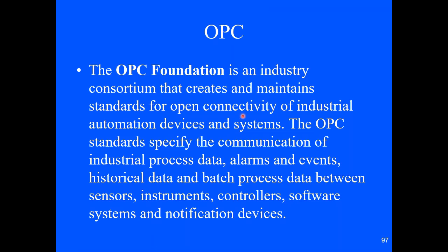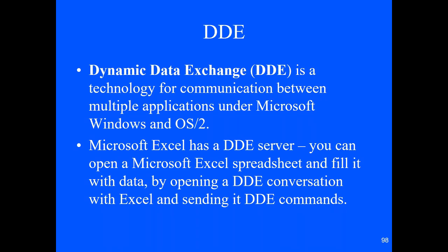OPC stands for OLE for Process Control, and it is a foundation. So you'll hear OPC DDE. This is how they set up how these devices are all going to talk and treat each other. And here's the DDE server. So that's dynamic data exchange. Something like Microsoft Excel has a DDE server.